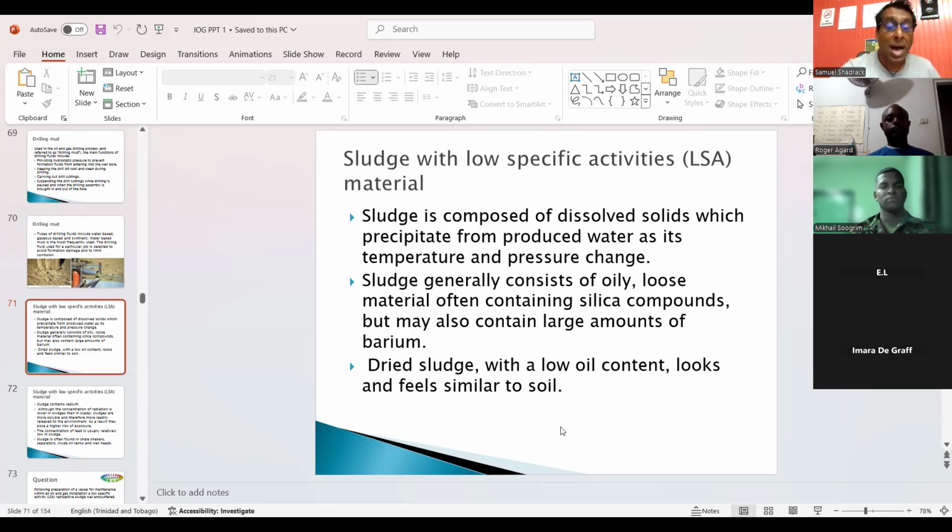So if you're cleaning that out, I remember doing it. I told you back in the day I worked with a contractor. They would, of course, ventilate the tank, but the way you clean it is with a shovel. There really isn't any other way. So a shovel and a wheelbarrow and you're cleaning all the sludge from the tank. I suppose there may be some sort of high pressure washing, but then the sludge is going to wash down somewhere. So the parts that are solid like soil, you have to get a shovel into that to get it out of there, and then you could wash at the base of it.